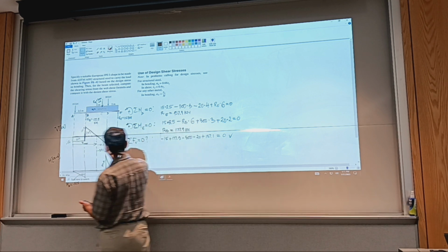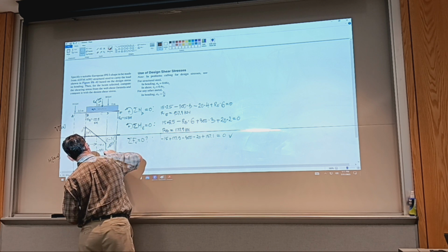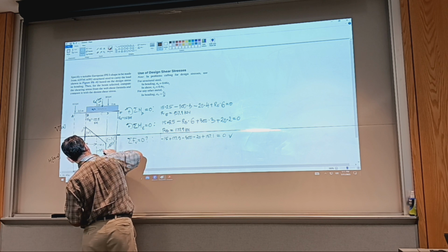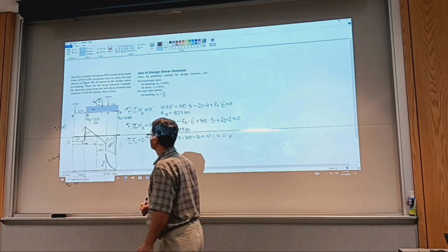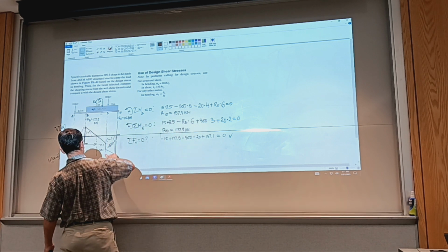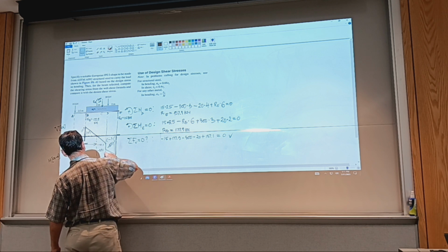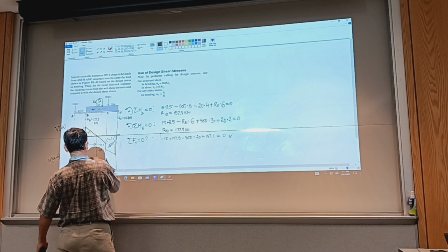Working from right to left, I was able to add this piece to the moment diagram. I'm overdrawing, and I know this magnitude here. It might be too high up, maybe the moment goes further up, so let's make provision for things that will happen here.